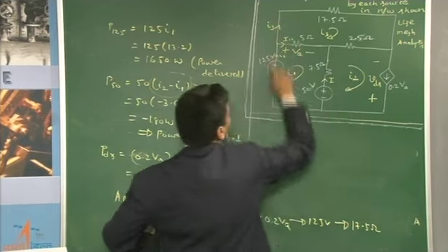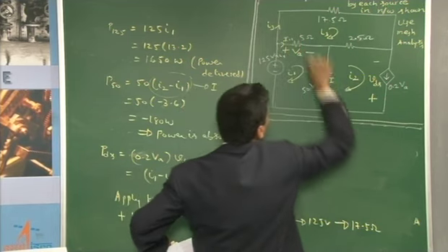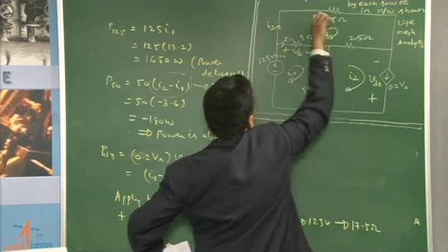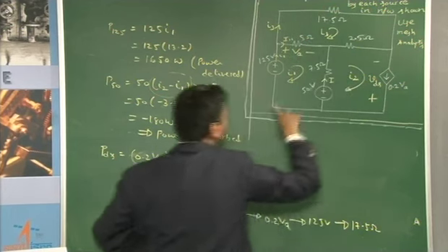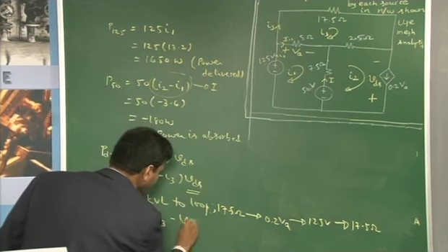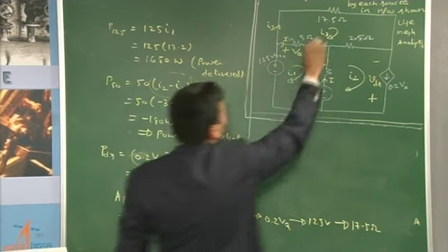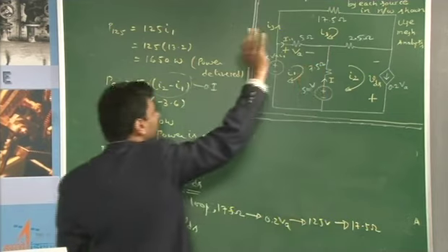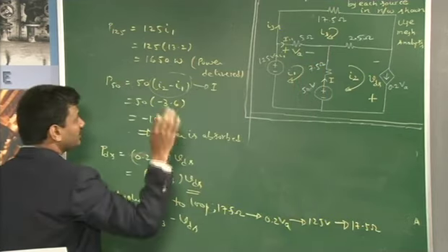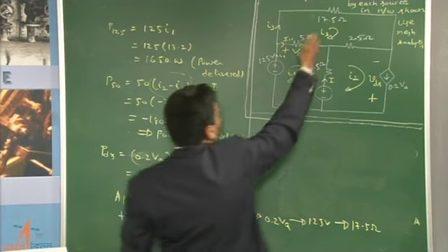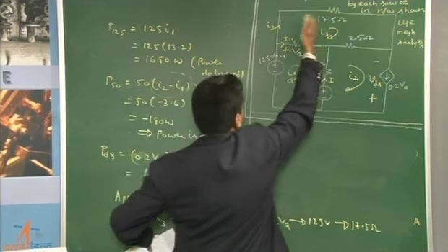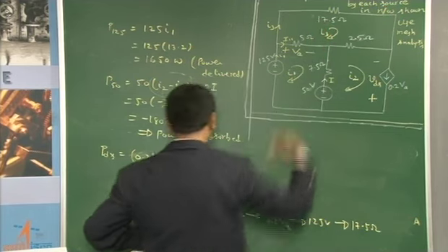So which is that particular current which is in alignment with the KVL direction through this resistance? It is nothing but I3. I3 is considered to flow in this direction, right? So I3 is in alignment with the KVL direction, so I3 I have written. Then minus VDS. So no need of identifying polarities of the potential drop across the passive circuit element. In the case of KVL being applied to any loop, let me reiterate how to find the drop: plus 17.5 into that particular current which is in alignment with the KVL direction.